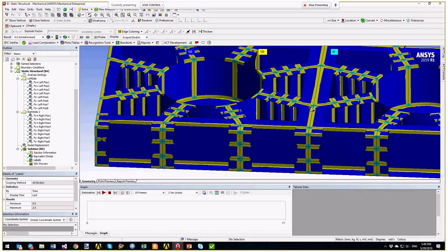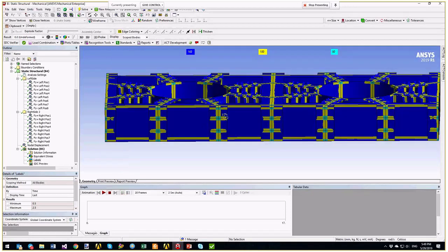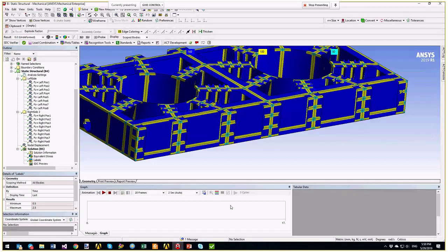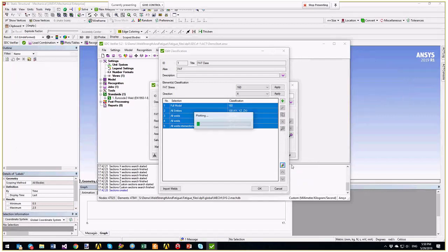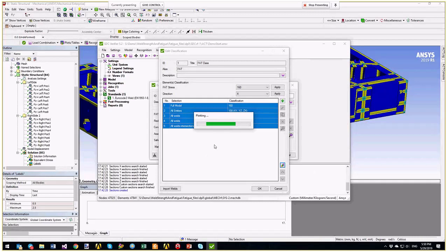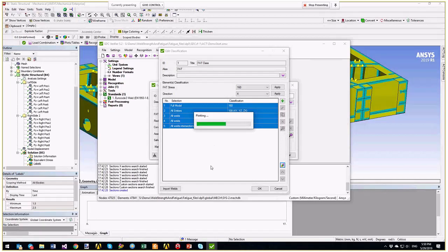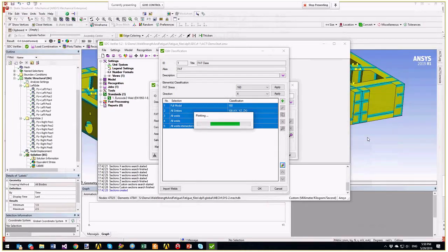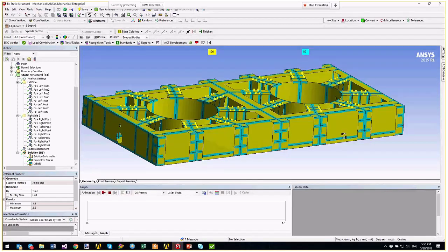As you can see, the full model is 160, parallel to the weld is 100, and where 2 welds intersect, those elements act perpendicular to both welds, so we need to use 80 for them. And if we plot, let's do one more plot for shear direction. Okay, for shear direction we have 100 for the full model and 80 for welds. So it seems to be correct.